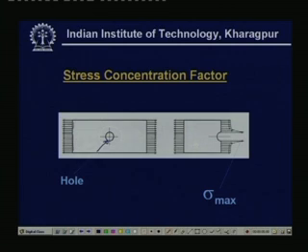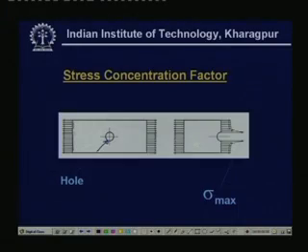That means the entire load, as I have taken a segment, you can understand from this stress distribution that this machine member was under a tensile load. So, when there are no discontinuities like a hole or notches or fillets, you have a stress simply P divided by A, equal to the nominal stress or the average stress, which is uniform.